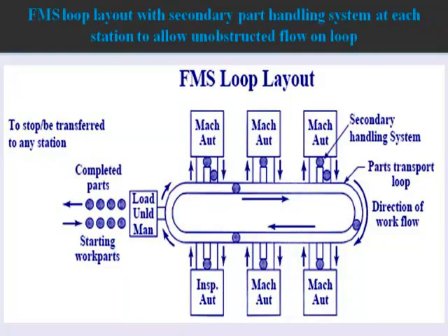This is a rectangular layout for recirculation of pallets to the first workstation in the sequence. The recirculation of pallets is sometimes necessary, because the machine is used for more than one process. Suppose process 1 is done on machine 1 and again process 20 is to be done on the same machine.